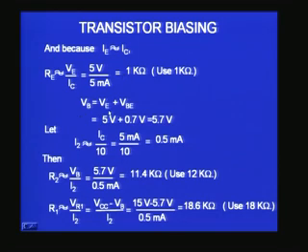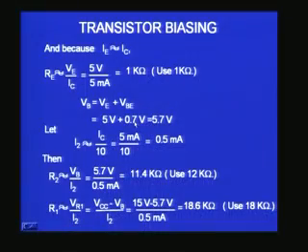And what is Vb? Vb is Ve plus Vbe. We wrote previously Ve is Vb minus Vbe. Now we are writing the other way. Vb is equal to Ve plus Vbe. Ve is 5 volts because we have just calculated or assumed, plus Vbe of 0.7 volts, assuming that to be a silicon transistor, and the total voltage Vb should be 5.7. So we want this to be 5.7. That means I must make sure that the R1 and R2 values are chosen so that the value at the base will be 5.7 volts. Then we have designed the biasing circuit according to our initial starting specification.